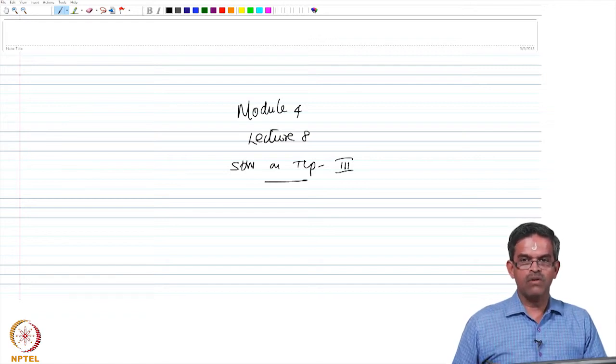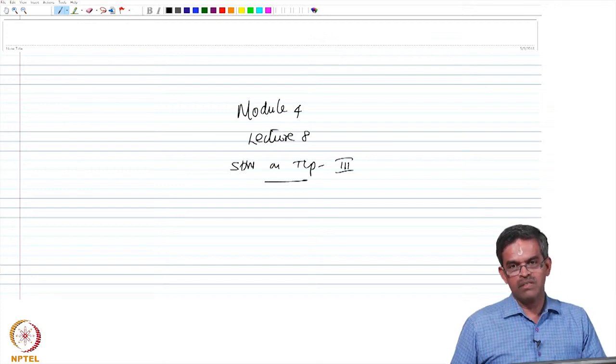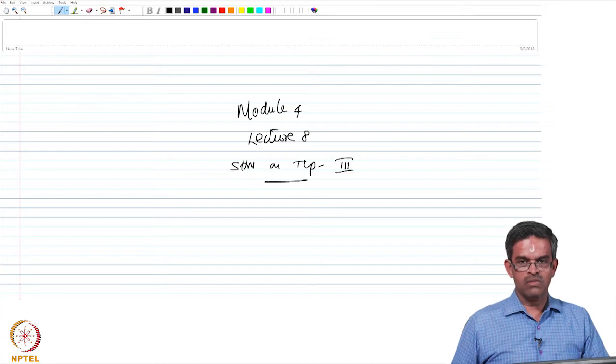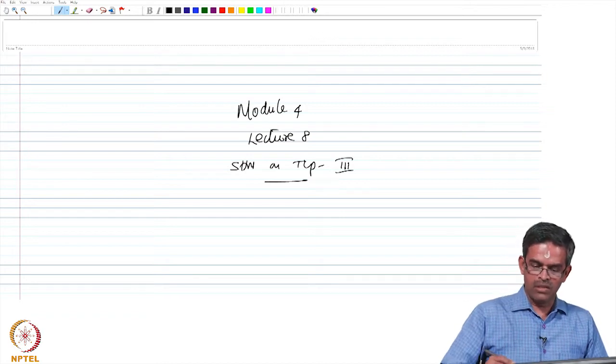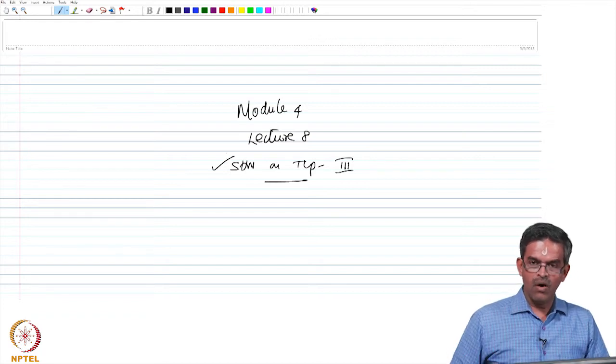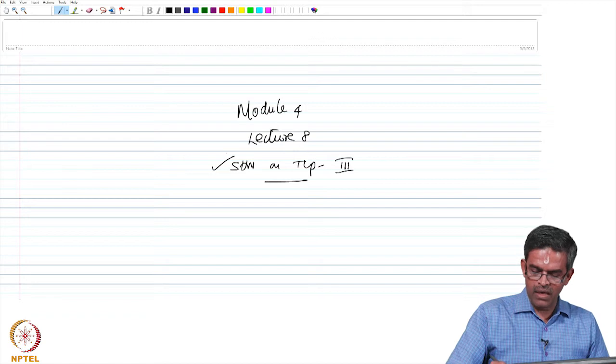As such, the TLP has not failed in the lab; an intended failure has been caused on the TLP model, and we are now designing a structural health monitoring system and an alert monitoring system to see whether the proposed SHM is capable of diagnosing the defect which has happened on the failed model, and is it able to communicate the failure to the user client server as required through SMS and email, etc. So, we are talking about structural health monitoring of a tension leg platform, which is lecture 3. We are investigating it on the lab scale.